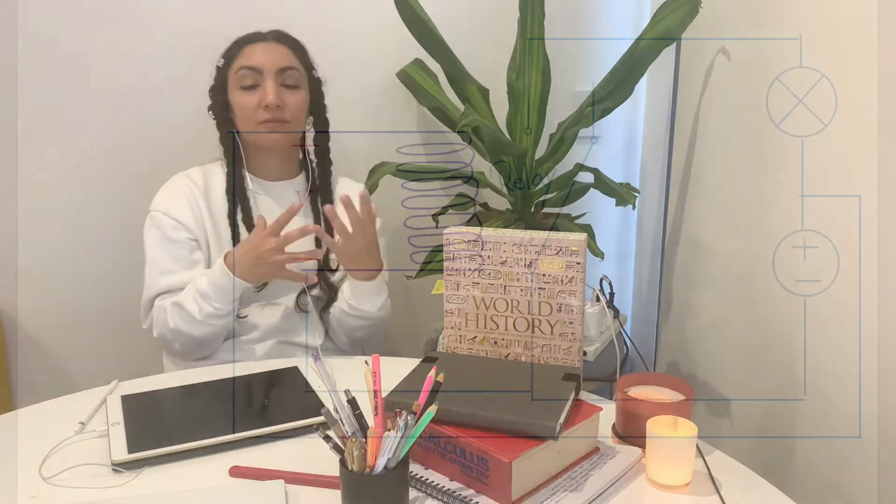So the relay is sitting there. Now there is a piece of metal here that is working as a connection to our circuit. As soon as the relay becomes magnetized, it becomes a magnet, right? So this piece of metal is attracted. Now the circuit that was disconnected by this distance is connected. So this is called a normally open relay, because the circuit is open, and when the relay starts working, it becomes closed. But if the circuit is closed, and by magnetizing or demagnetizing the relay you make the circuit open, then that's called a normally closed circuit or a normally closed relay.